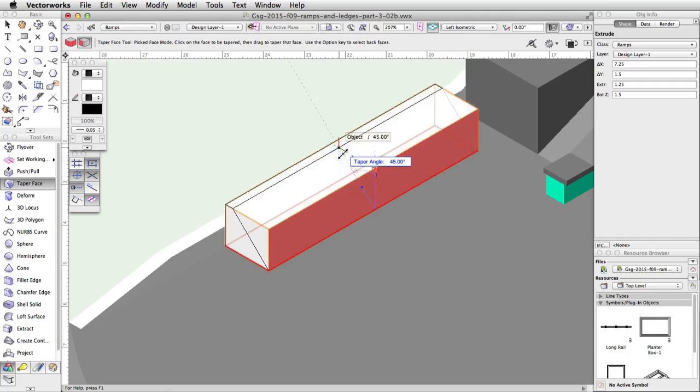Note that there are multiple snap points in this area. You may find it difficult to set the angle to 40 degrees. However, if you hold the back quote key, you can temporarily suspend snapping. This will make it easier to set the angle to 40 degrees.